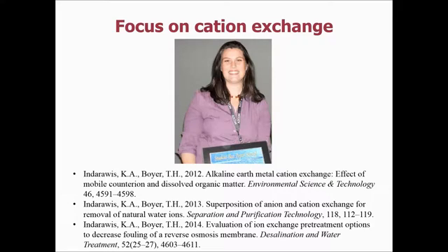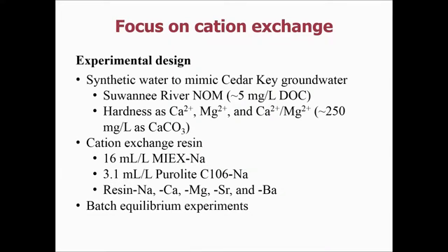So then we felt at this point we needed to study deeper the cation exchange piece of combined ion exchange. And so we did that by working, again, with the Cedar Key groundwater and also making some synthetic waters to mimic the Cedar Key groundwater. In this case, we looked at both this magnetic ion exchange resin, which is a little more of a research product, and then looked at a standard off-the-shelf cation exchange resin that a plant might use now for softening.